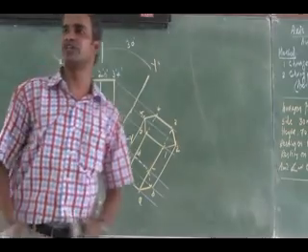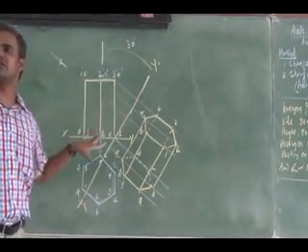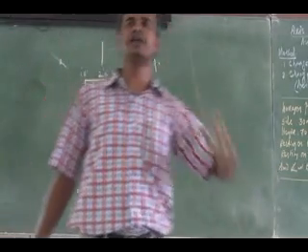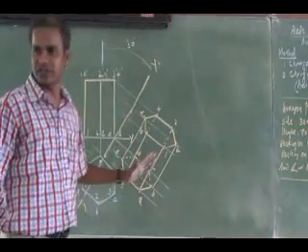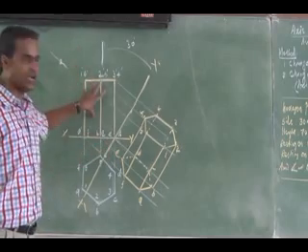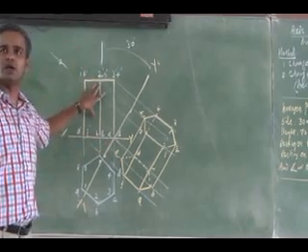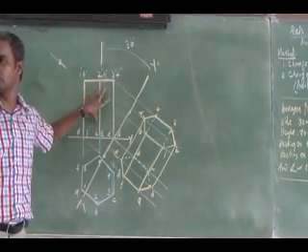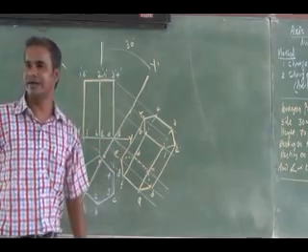This is how I will have my projection. So in this change of reference line method, the reference line will be redrawn to the tilted angle of axis inclination and to the exact position, right? And the front view, what you have got in the simple orientation, that will be used as the final front view, right? And the top view will be obtained like this.